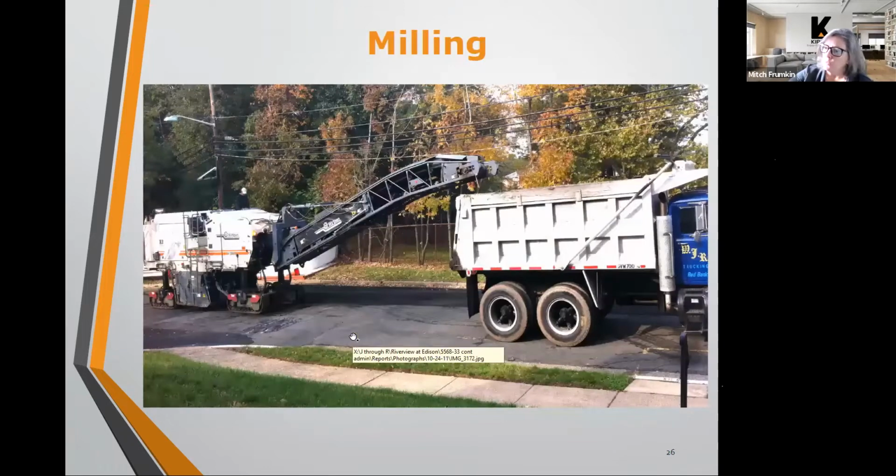So I'm just going to go through really quick. Here's milling. It's very noisy, very messy. This is where they mill off the top course of the pavement. Here's the milling machine. They mill it into the back of the truck and haul it away.